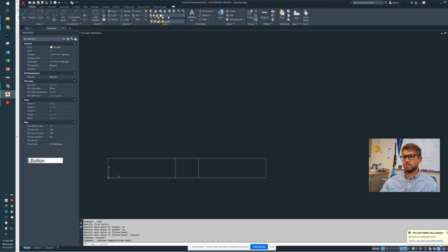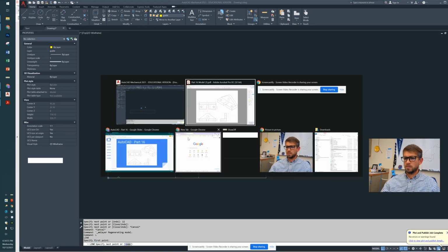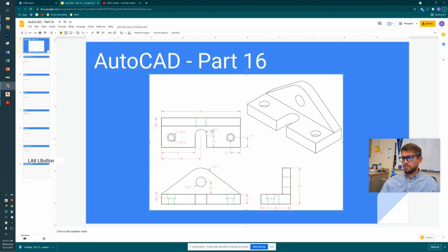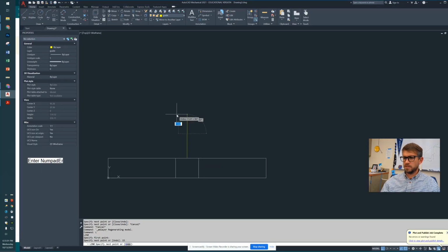So I'm going to switch over to my guide layer. I'm going to draw a line up from the very center point. Okay. I already had my O-snap on. Remember, you could use O-snap to get midpoints working. And from this drawing, we need to go up 15 to get to the center point of that. 15. Switching back to my 0 layer.